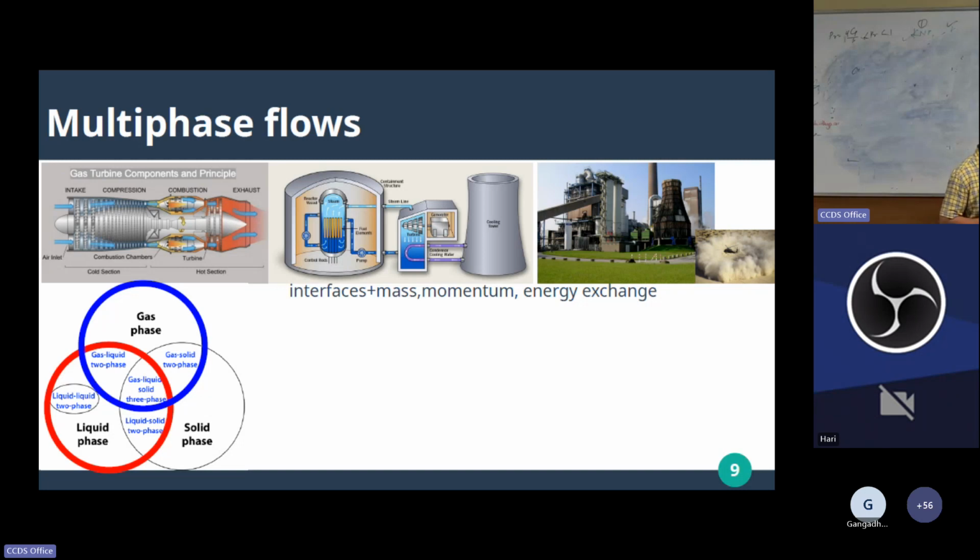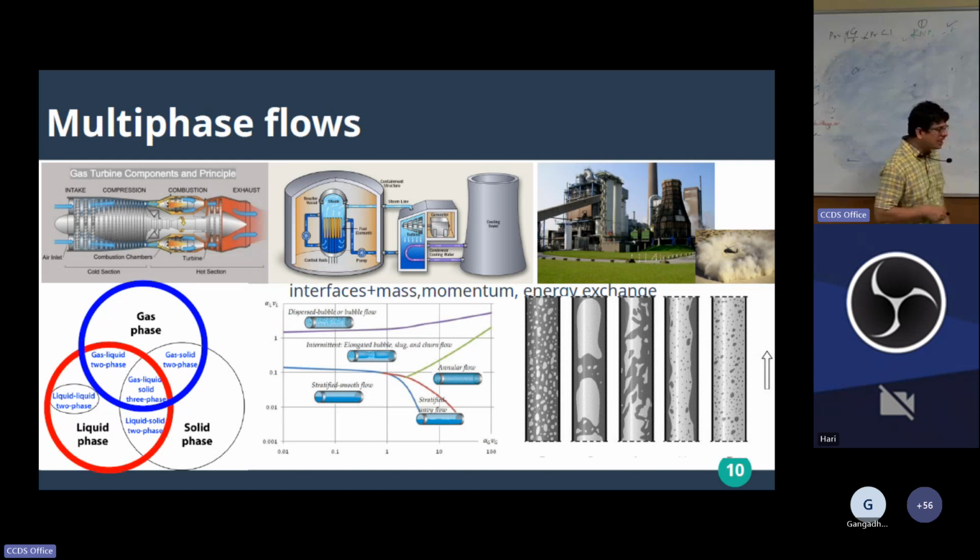This is what we are going to look at. Though we are saying multi-phase flows, handling gas to liquid, liquid to solid, solid to gas, you have different kinds of solvers. And it's not just one solver that will be suitable even for gas-liquid. It has different varieties. That's what we are going to first have, a broader perspective. Even if I am saying something like interFoam, is that generic, or are there much better things, the terminology. So let us look only at gas-liquid.